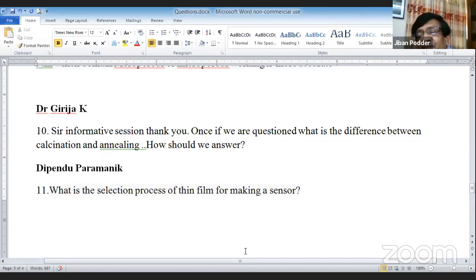Only the temperature and bonding-related changes will change the properties, without changing the main component, without removing or oxidizing it or releasing volatile product. We need annealing keeping the substance the same. But calcination, you have to change many phases because of high temperature, and that will change the properties also.